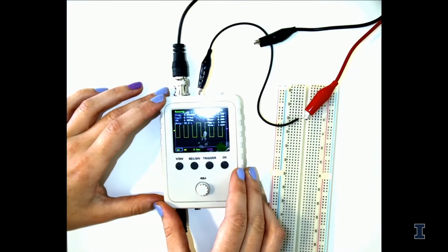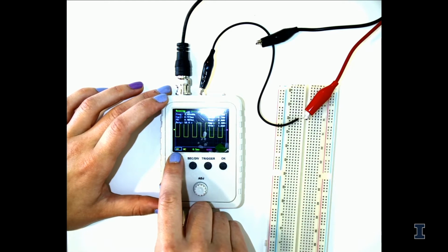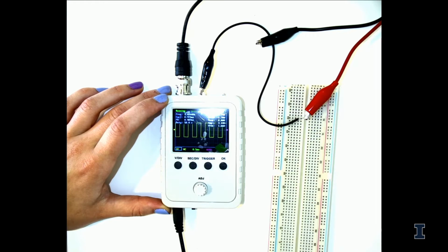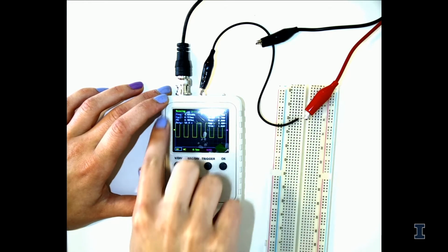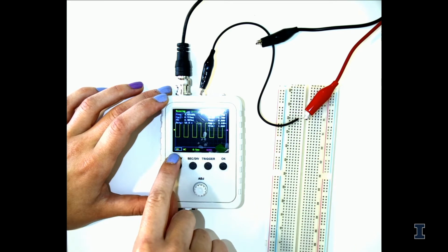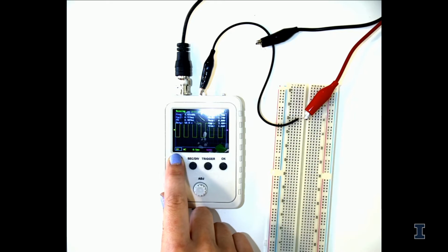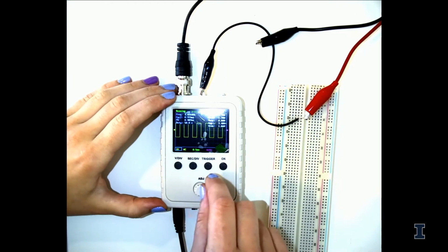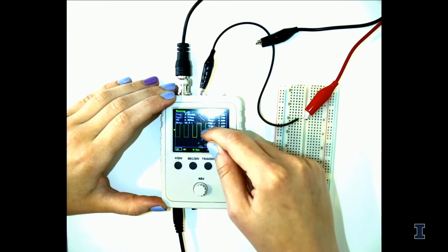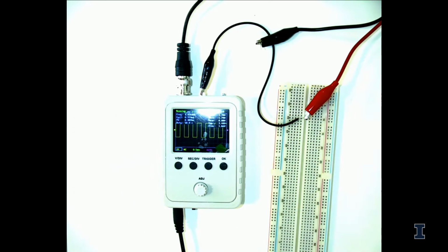And it's a 1 kilohertz signal, and we can tell that because at the bottom you can see what your measurement values are. The oscilloscope screen has a grid on it, and on the left we see 1 volt. That means that your Y increments are in 1 volt. We can see here that it goes about 1.5 squares high, which means your signal is alternating between 1.5 volts positive and 1.5 volts negative.